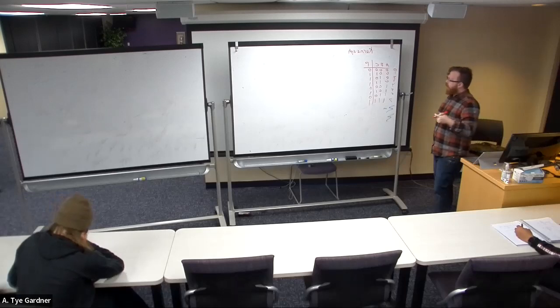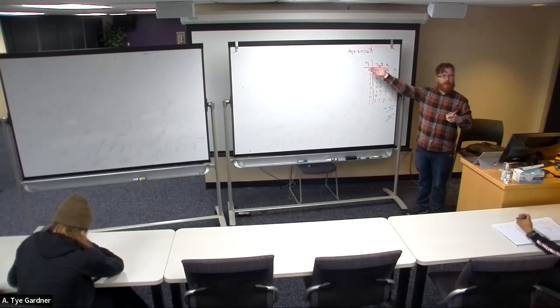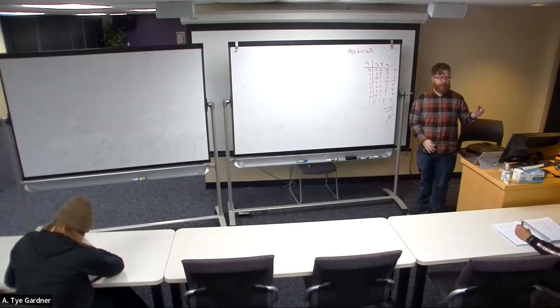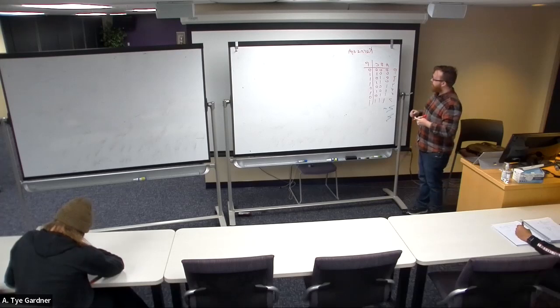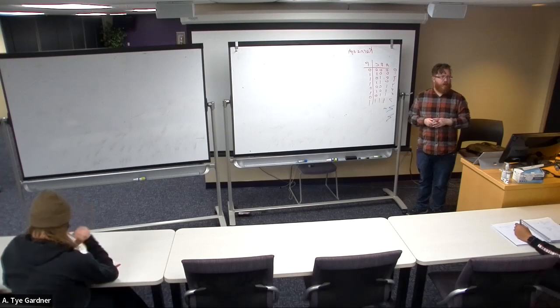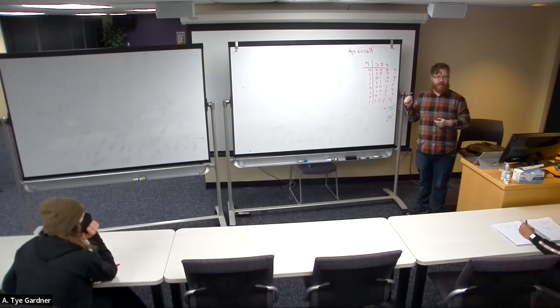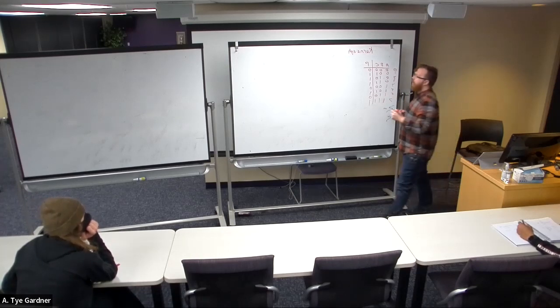So what this is saying is that P will be 1 if the input ABC is a prime number. Okay, this detects or asserts a 1 if there's a prime number. And we could go ahead and design the circuit using a sum of products expression, right? And we have the sum of products expression.